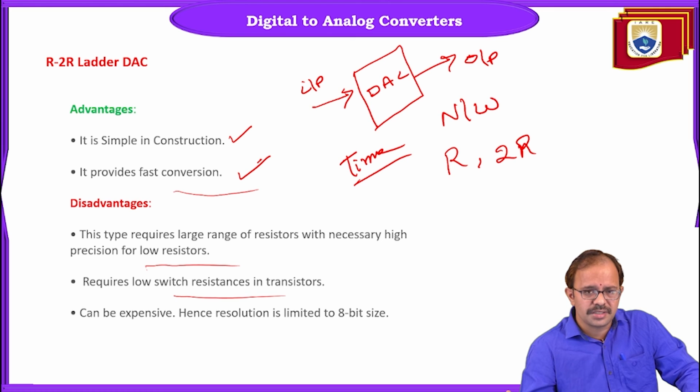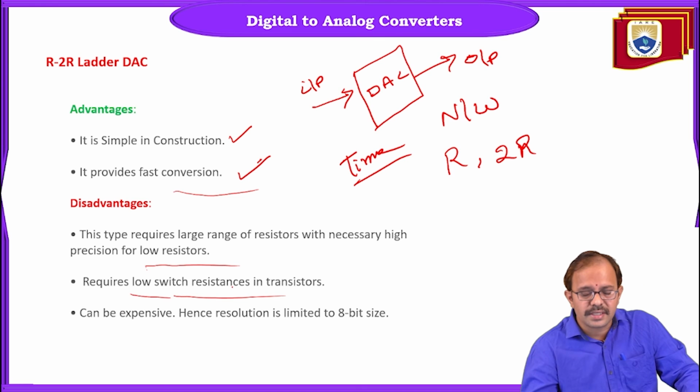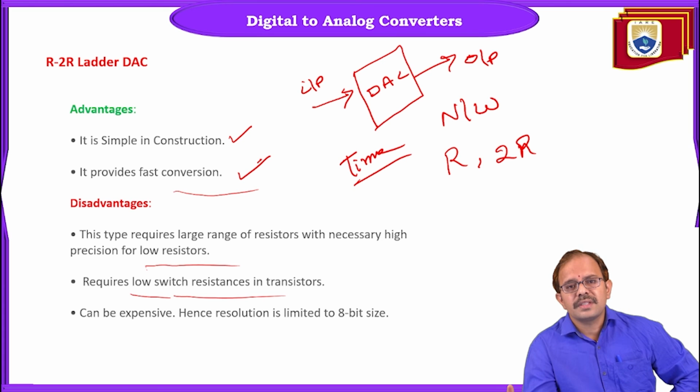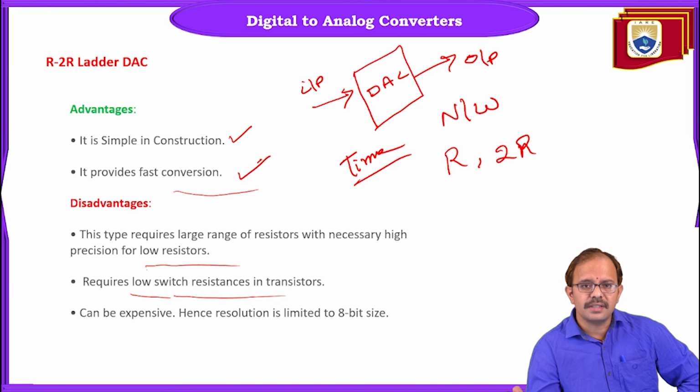Whatever element we use as a switch, it should possess a low resistance. Otherwise, if the resistance of the switch used in the design is fairly high, the impact of this resistance must also be considered in the analysis, and it will affect the performance of this DAC.